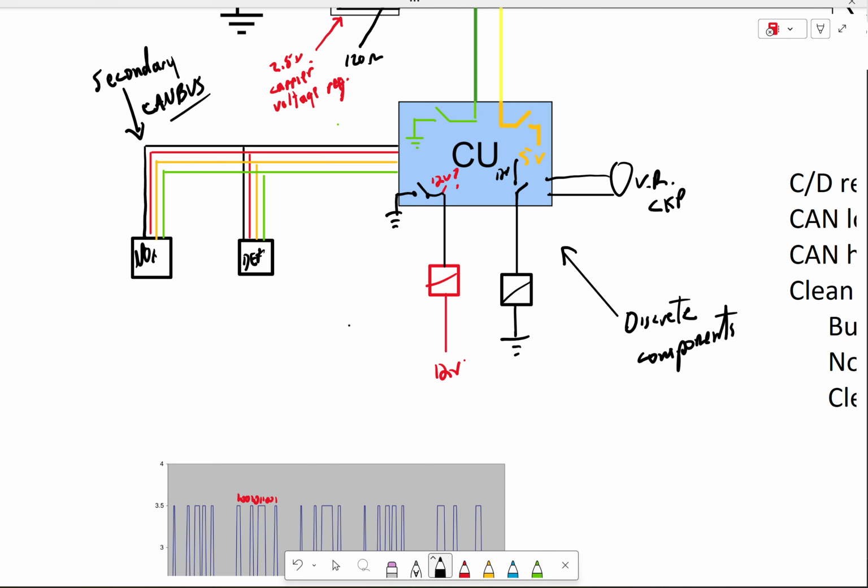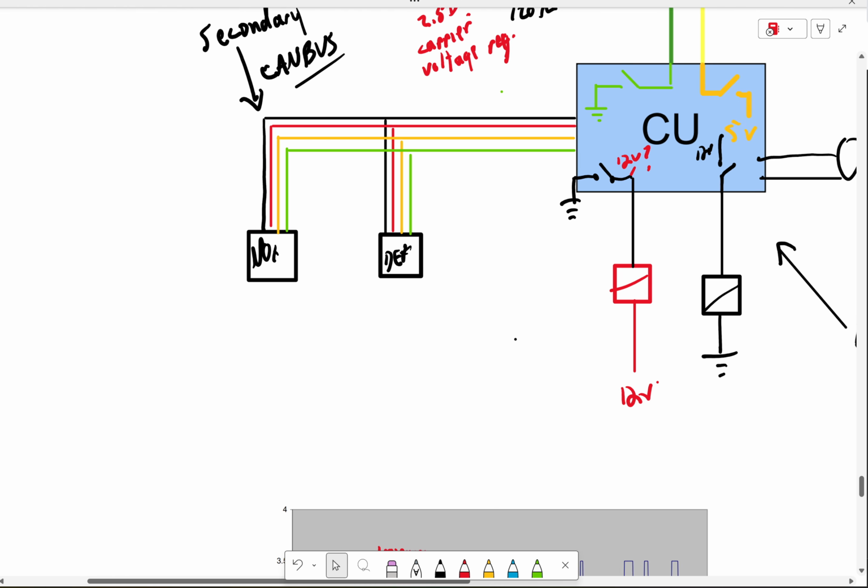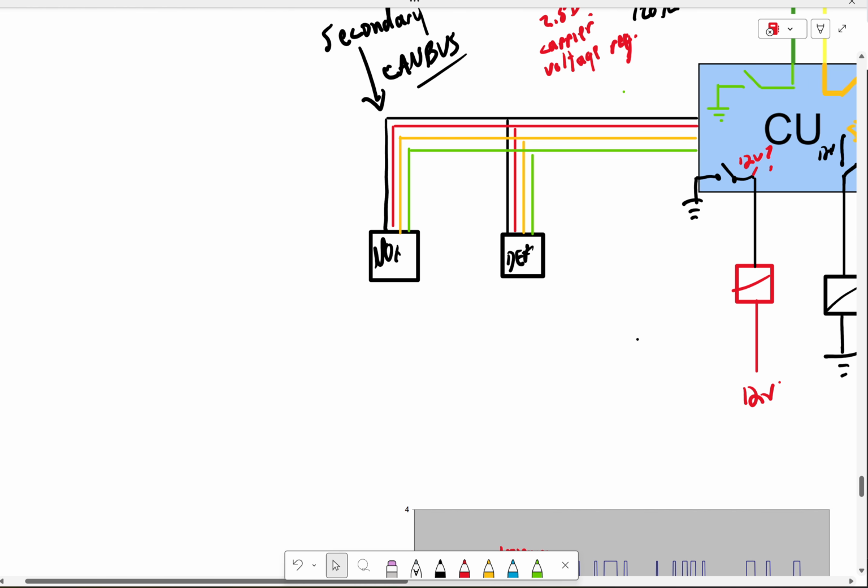Okay. So discrete components, those are ones that basically have a single connection to the controller. Networked components, over on the side where we have the secondary CAN bus devices, those ones are not discrete because they communicate jointly with other components on the network as well as the main controller that they're hooked up to. So those are not discrete. Okay, so for instance, this NOx sensor here, this is what we could call a smart sensor.